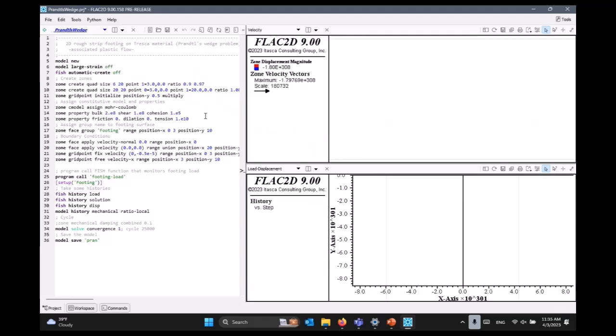So this is a data file. First, we create geometry. We specify material properties. This is boundary and initial conditions. This is a little bit of scripting to define where we calculate forces at which positions near the punch to calculate bearing capacity. Then we track histories of different parameters at different locations. And basically, we just solve it.